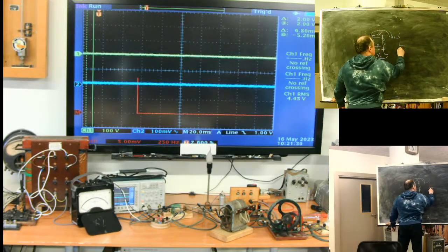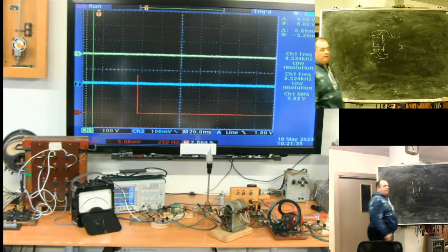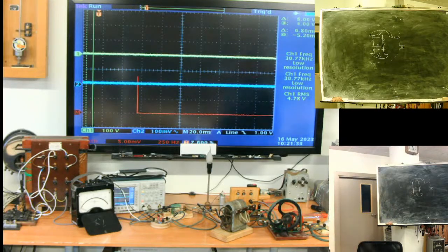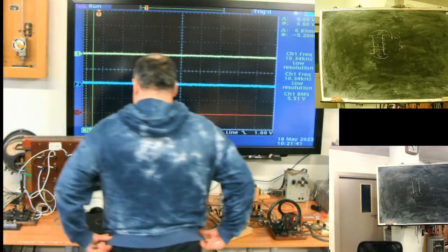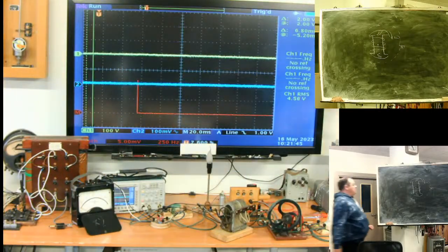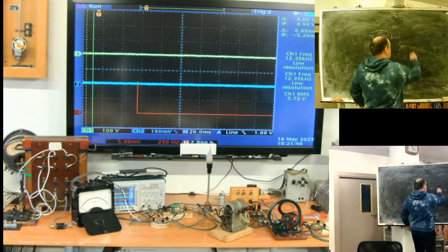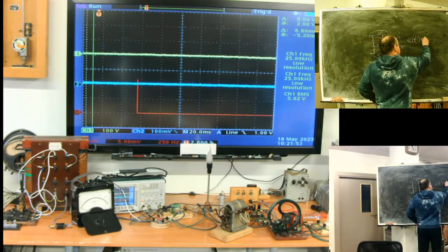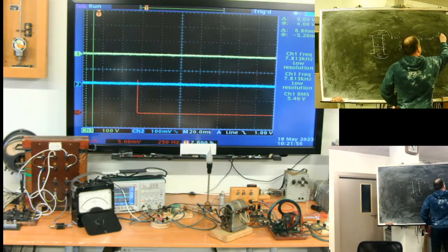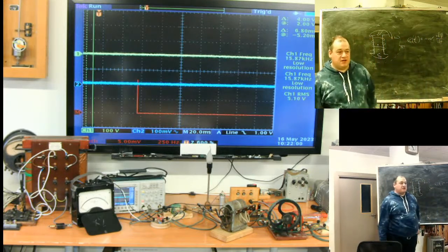We have the so-called stator, and here one wire of the stationary winding. What will be the voltage induced here? Minus number of turns and first derivative of the flux.